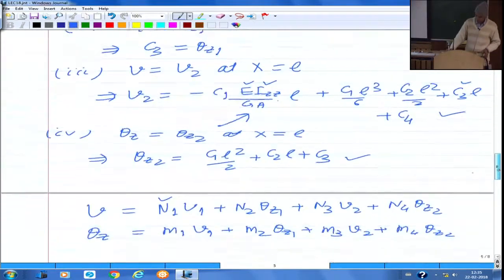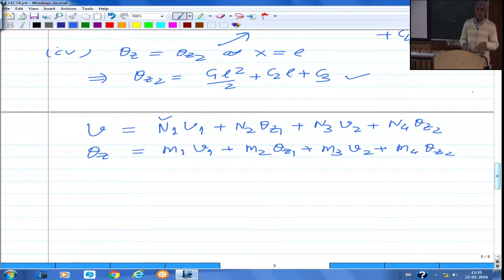For you to cross check, I have got this stiffness matrix for this element. So you can finally cross check the load vector, of course you can derive, and the internal load vector remains the same, minus S1, minus M1, S2 and M2, if you are not considering U naught. So K is based on this interpolation.